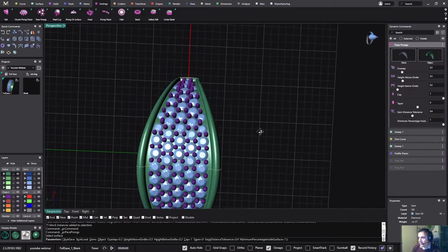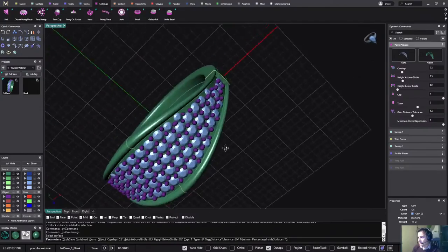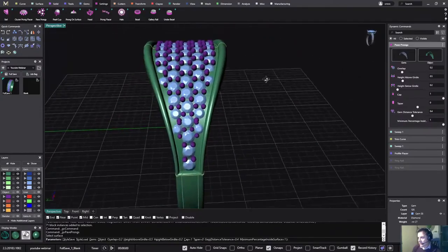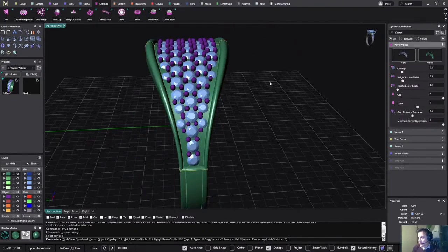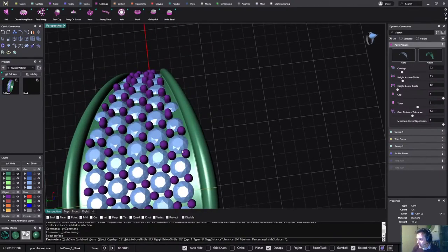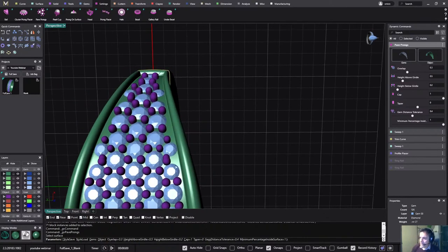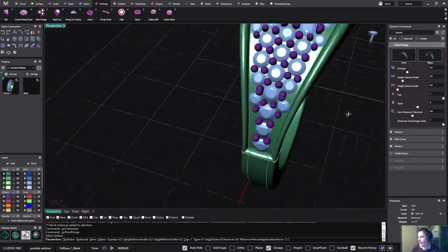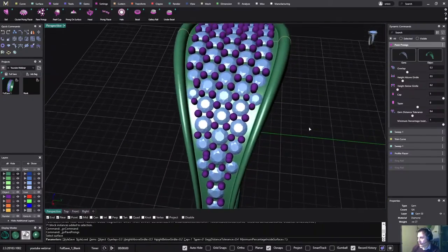So in just one go, we already get all this. All right. And I really believe that this is very, very fast and very good. If you want to go a bit deeper, a bit farther inside the stone, instead of the overlap 0.2, we go to 0.3. And you will see how all of the prongs grow up, and now we have more metal inside the stone. So the setter can play a bit more with the metal.